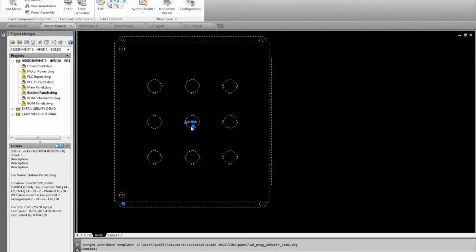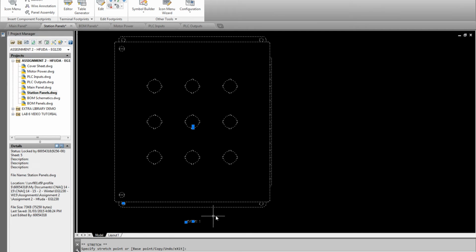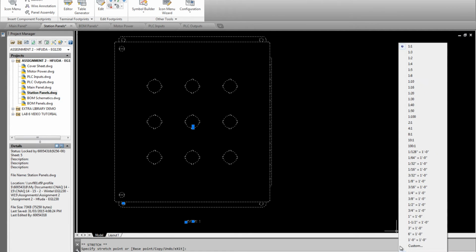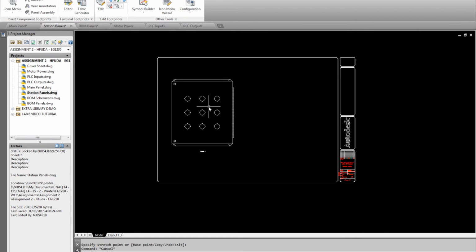You can click this and then move it out to the bottom and go to the properties and change the size. Line type scale is 1, position is 1. Anyway, you need to get your annotation scale and so forth, as we have done before. Let me concentrate on how to fill these out.